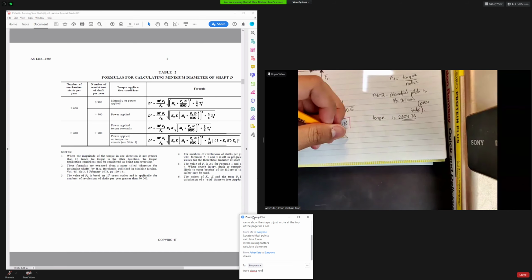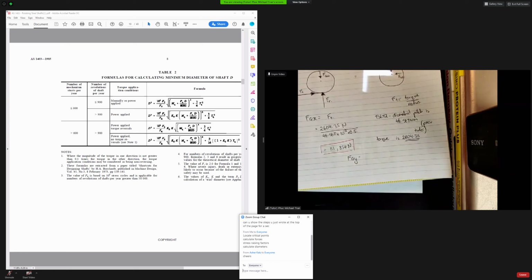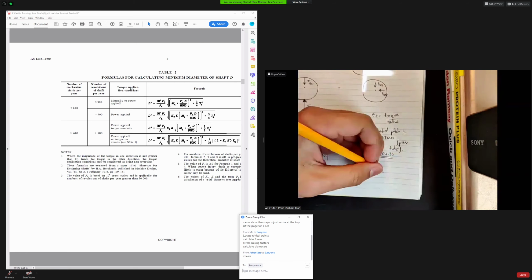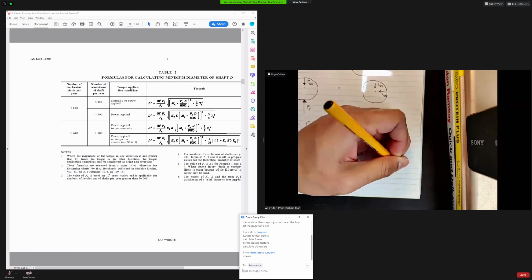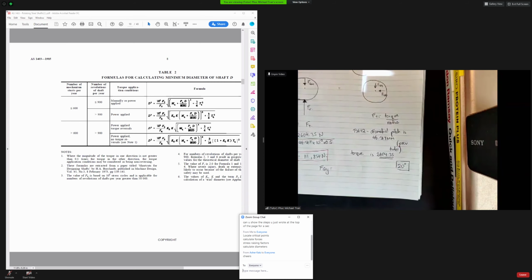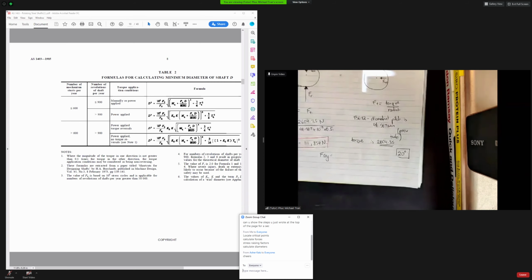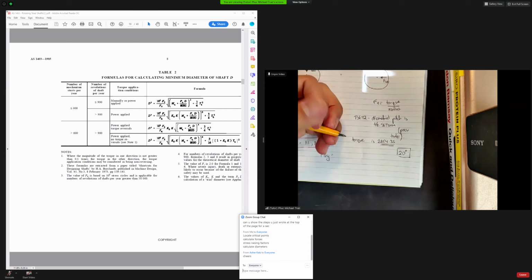Next, FGY. Because there is a relationship between FT and FR, which is a pressure angle, and the pressure angle of the gears that we choose is 20 degrees. So the pressure angle is the angle at which the gears should be put together at.